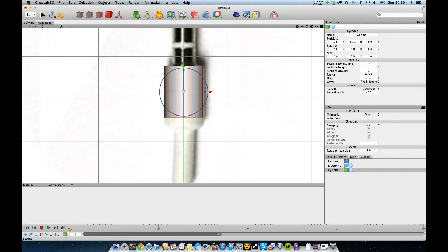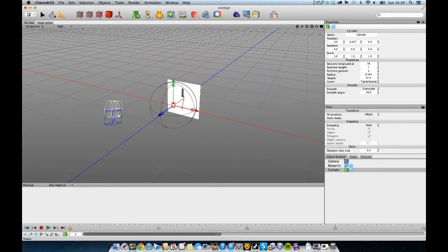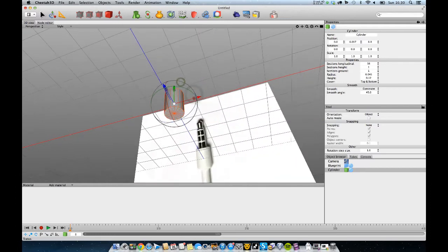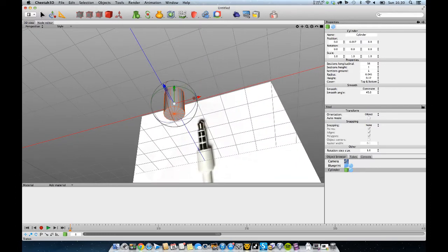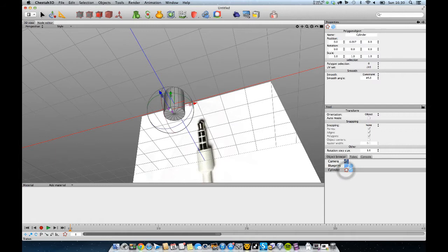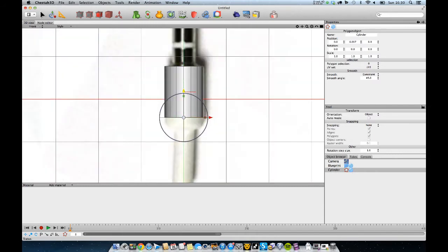Really, from here on in, it's about extruding or covering and just pulling and transforming. I'm just getting that rough shape there. So I'm just going to grab these bottom polygons a minute because it's not quite the right height. Collapse my mesh by double clicking, grab these bottom polygons, and I'm going to come back into that front view, keyboard 3, just bring that down to the edge there. Okay, that's what I wanted.